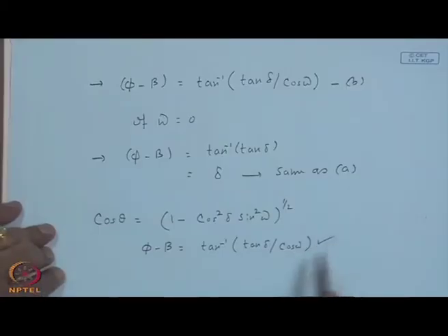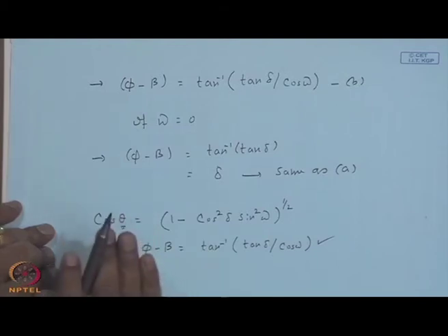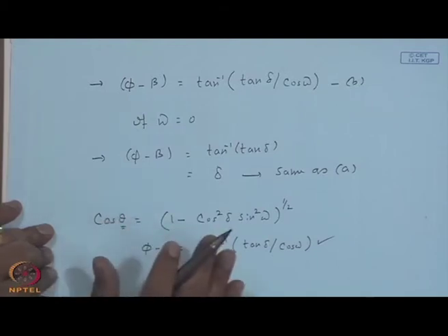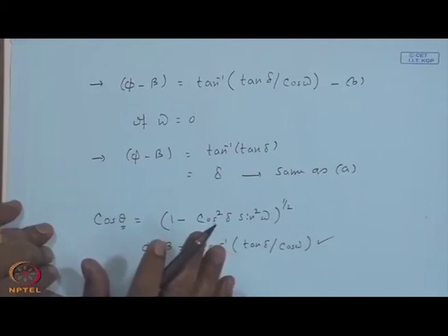In other words, it swivels around the east west axis such that beta is adjusted with this equation and your theta is a minimum. Theta will be 0 only at noon time, but theta will not be 0 at other times for this mode of tracking.